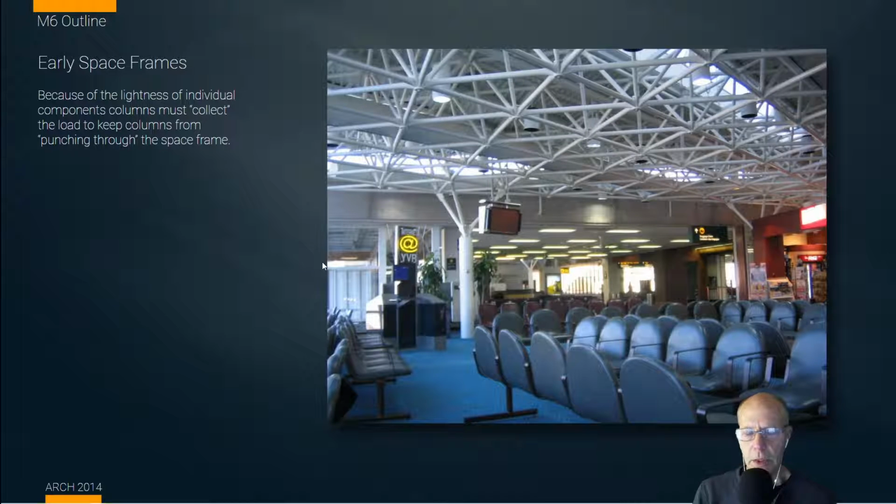This puts it a little bit in the context of history. This is a space frame system supporting a flat roof in an airport, probably in the 70s. So space frames aren't new. We still have the idea of adaptive columns. Adaptive columns like this with these fingers coming out are important in order to bear the load. Any single node on a truss is not able to support the full load of the frame system, so we have to catch a few nodes in order to support it.